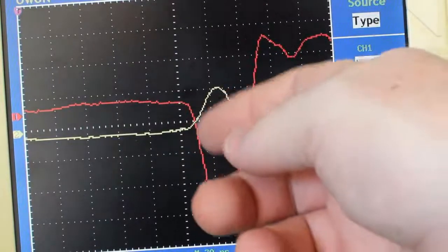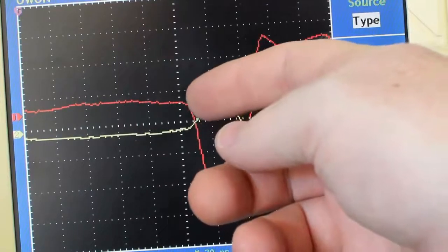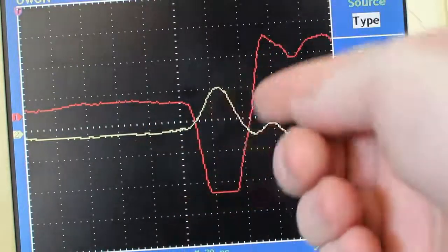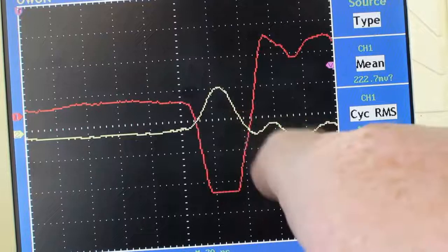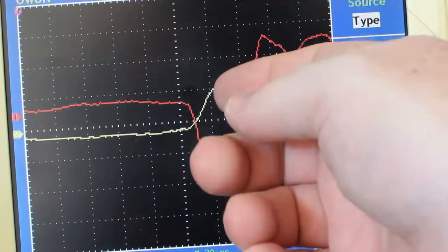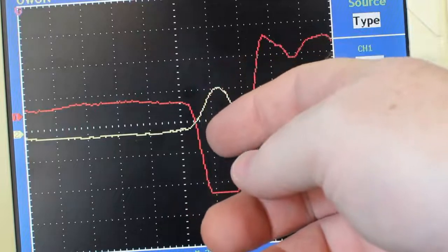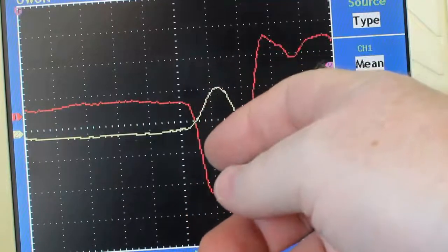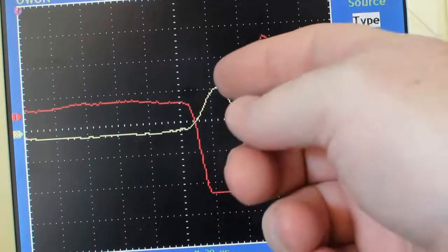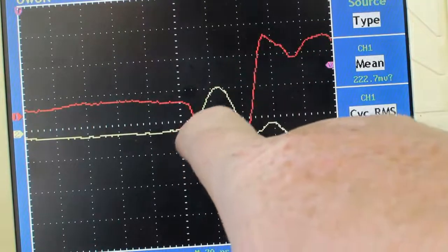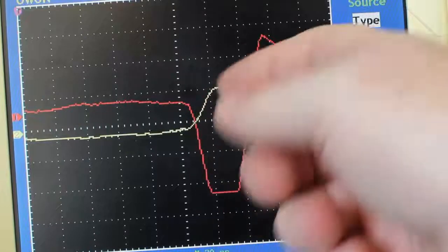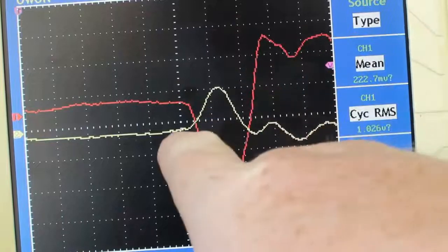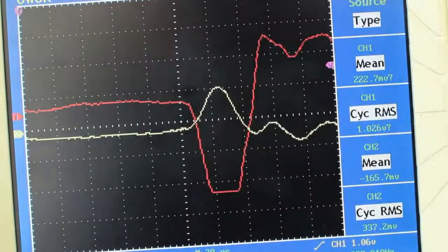So if the coils were exactly the same, if the delay and everything was exactly the same, then we'd have exactly the same curve, exactly the same waveform on both points here, but we don't see that. We see that this coil is responding in time to the change in this coil. Remember, this is current. So anytime there's a change in current, it creates a voltage, and this coil over here is responding with a curve up here that is responding to this fall over here. So there's a change in time. It takes time for that to happen.